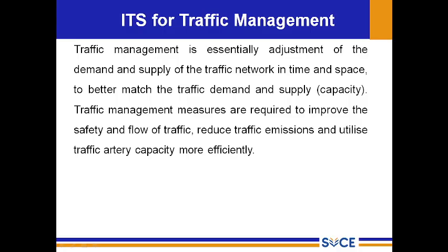So we need to compare the demand and supply. The V by C ratio, the volume by capacity ratio, should always be less than 1, even during peak period. Then only can the road cater for the required demand. Traffic management measures are required to improve the safety and flow of traffic, reduce traffic emissions, and utilize traffic artery capacity more efficiently.